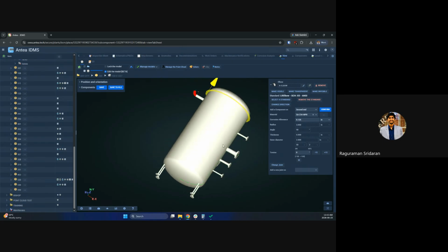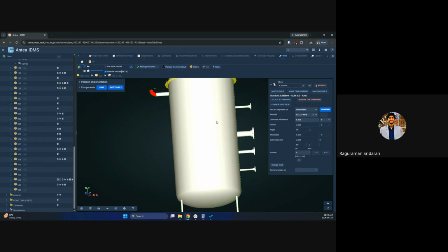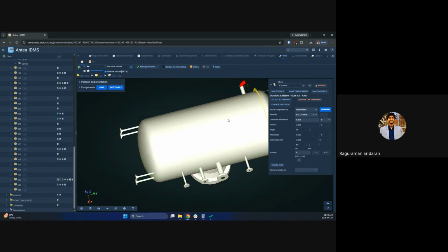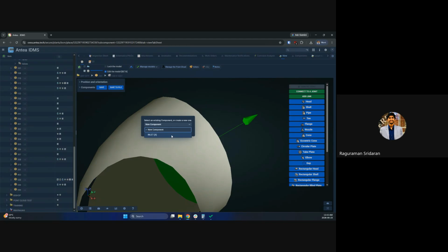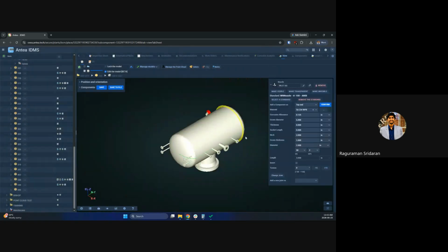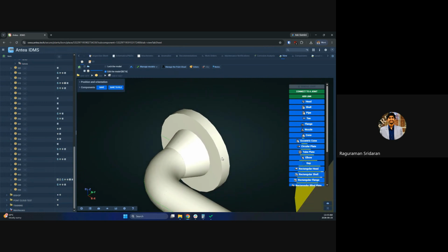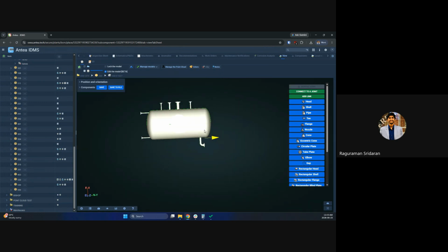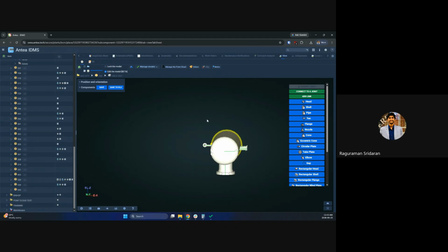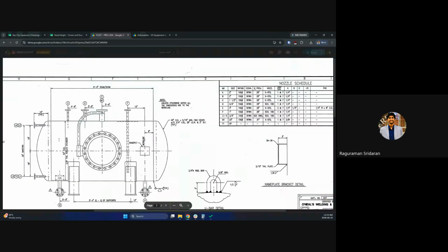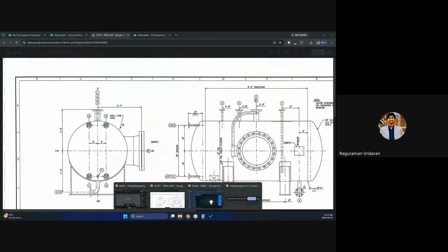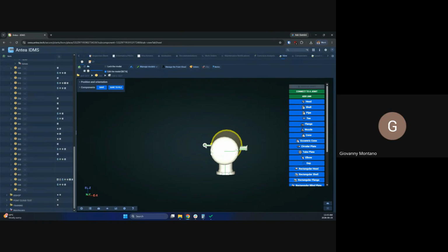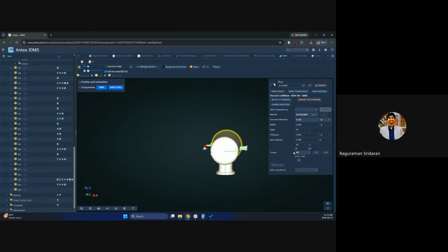The only thing we need to see here is the orientation is towards the right head. We will adjust that. I'll show you real quick. I'll add the nozzle we already created. Since we already created and deleted it, you can see I just chose from the drop down and say confirm. One thing we have to adjust is which direction the nozzle needs to be faced. It seems it should be close to the other side of 90 degrees, so which means 270. So we say 90, it's going the other way.